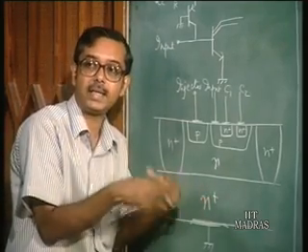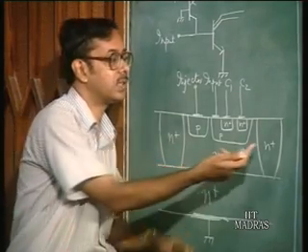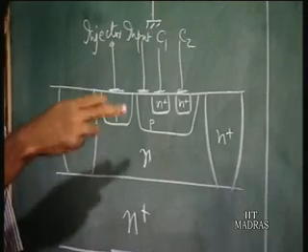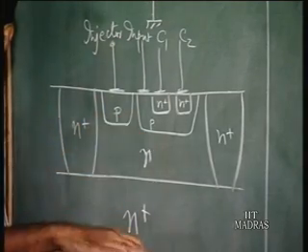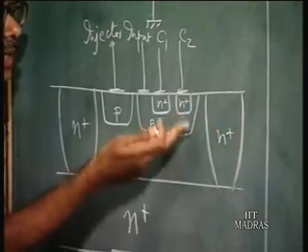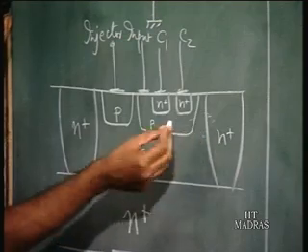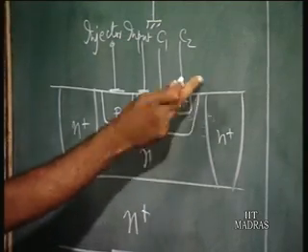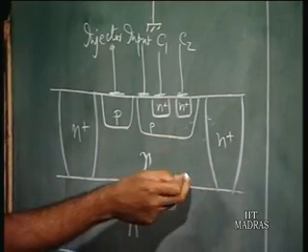That you can do by increasing the doping concentration on the emitter side, because if the emitter doping concentration is increased, the minority carrier is proportional to Ni squared by Nd. So, that is reduced. By making this n plus, you are reducing the holes injected into this side of the emitter, because you are reducing the minority carrier concentration here.